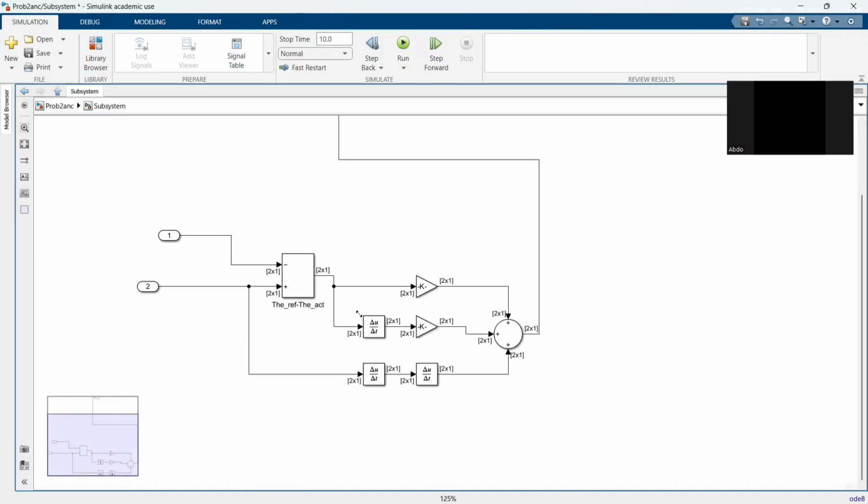Here, the derivative term is used to add velocity and a damping effect. This helps us reduce the oscillation and improve the response. So it acts as the PD controller, and we will see it in problem 4. In simple words, the controller uses the position error and the rate of change of error to generate the desired acceleration and torque command.